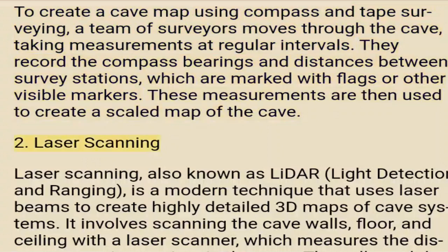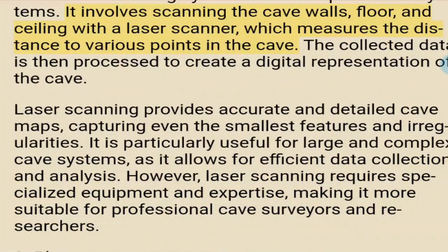2. Laser scanning. Laser scanning, also known as lidar, light detection and ranging, is a modern technique that uses laser beams to create highly detailed 3D maps of cave systems. It involves scanning the cave walls, floor, and ceiling with a laser scanner, which measures the distance to various points in the cave. The collected data is then processed to create a digital representation of the cave.